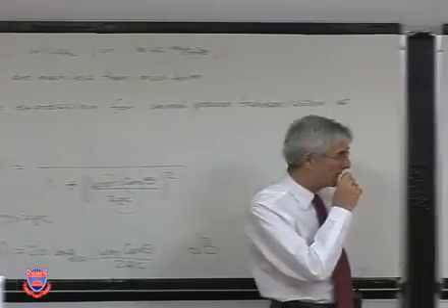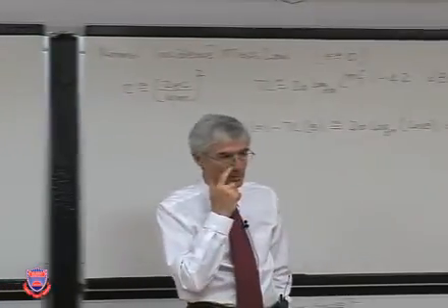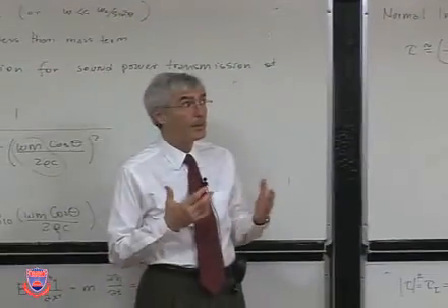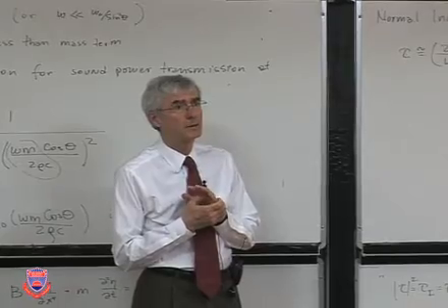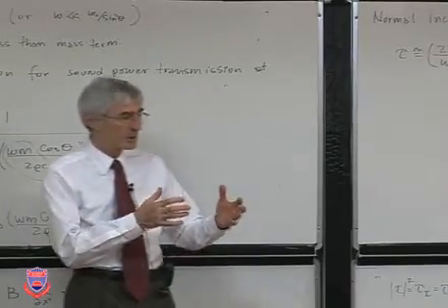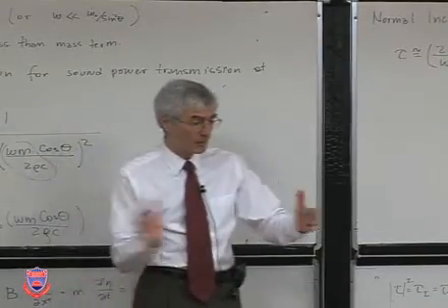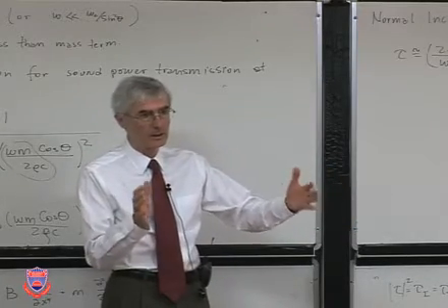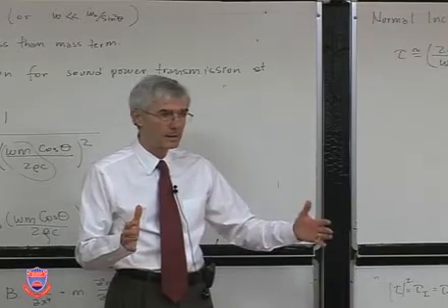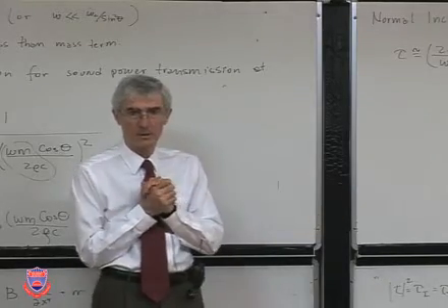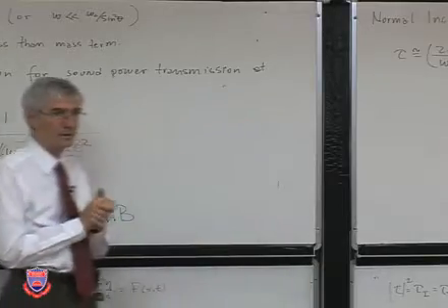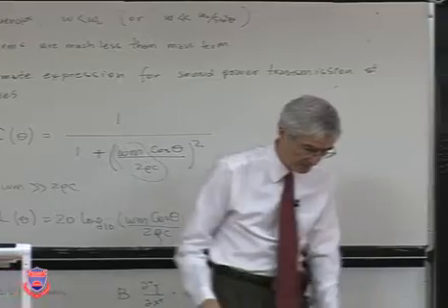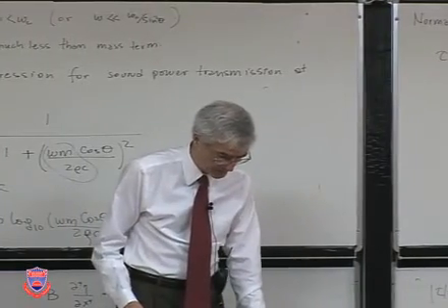In fact, something to keep in mind is sound radiation at low frequencies is, how shall I say, mass dependent. In other words, if you want to prevent sound from transmitting from one side to the other of a wall or plate, you increase its mass, nothing else. That's what it is. At high frequencies, of course, it's stiffness dependent, just like the single degree of freedom oscillator that I described a little earlier.